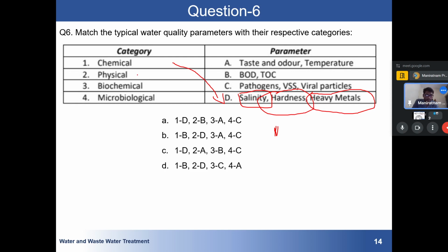Physical means, what will happen is that initially we use some kind of aeration tank so that sufficient oxygen can be given to the system. Generally in groundwater the organic matter is very less, but still if something is there, it can oxidize. So this physical method is used for removal of taste, odor, and temperature. Some external mechanism is also used to control the temperature of your water.